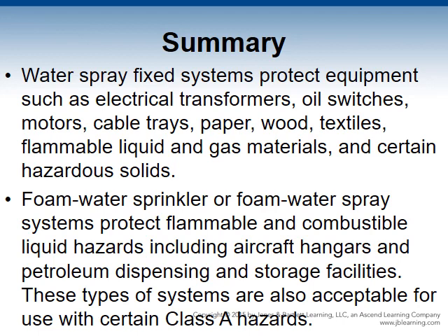Water spray fixed systems protect equipment such as your electrical transformers, oil switches, motors, cable trays, paper, wood, textiles, flammable liquids and gas materials, and certain other hazardous solids. Foam water sprinkler or foam water spray systems protect flammable and combustible liquid hazards, including aircraft hangars and petroleum dispensing and storage facilities. These types of systems are also acceptable for use with certain Class A hazards.